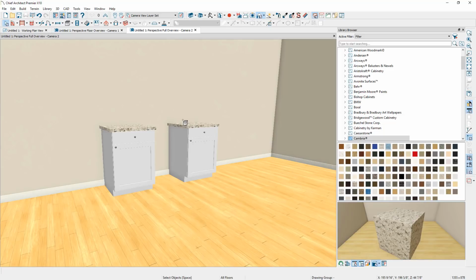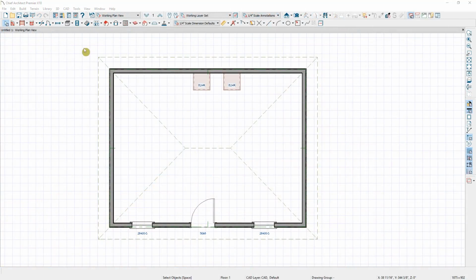You can change all of those defaults, and then when you're finished, you can save this as a template plan. It's very important when you save a template plan that there are no architectural elements inside of the plan. In this case, you wouldn't want walls or the cabinets, anything in there, because as it begins a new plan, it's going to open that up. Let's go through and delete the components, and then we'll save this as a template plan. Now, I don't have a lot of information here, so I'm just going to go into the plan view.